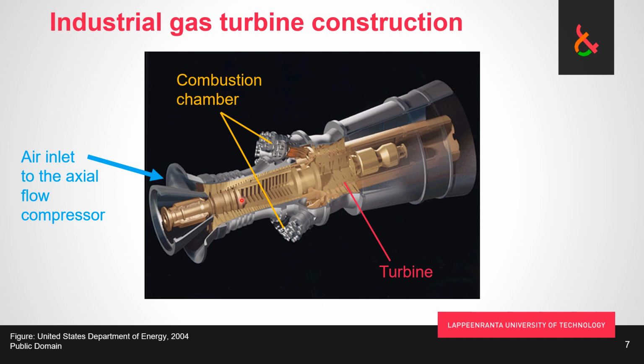It is much harder to force airflow towards the higher pressure. We can only increase the pressure so much per stage, whereas in the turbine, basically we are going in the natural direction of the flow, so it is fairly easy to design in a couple of stages with a lot of pressure drop.